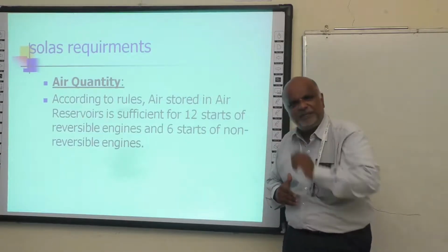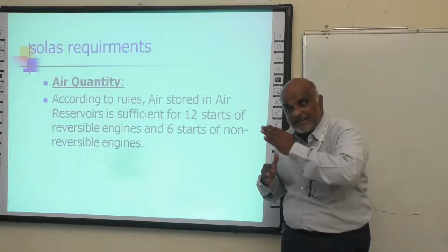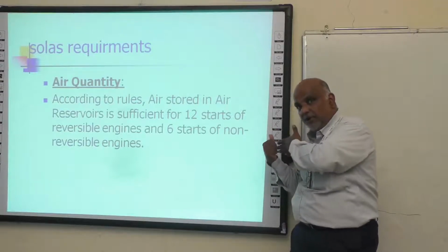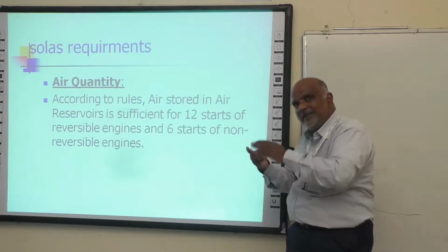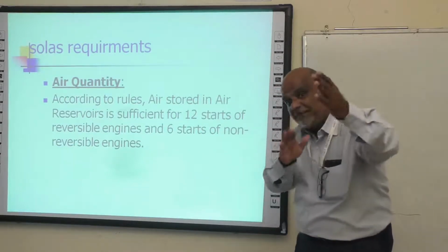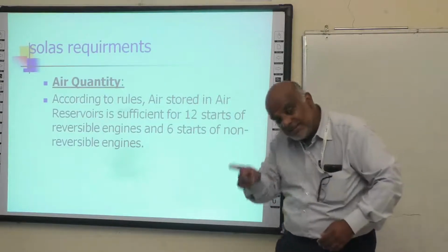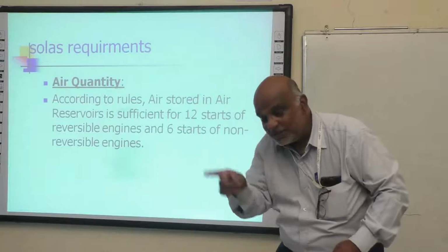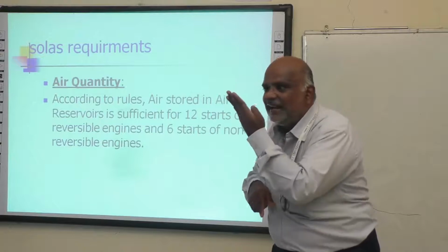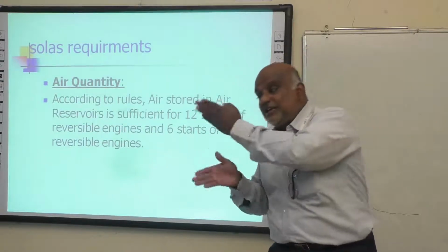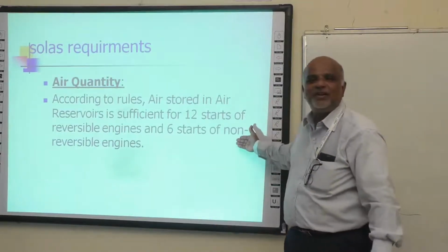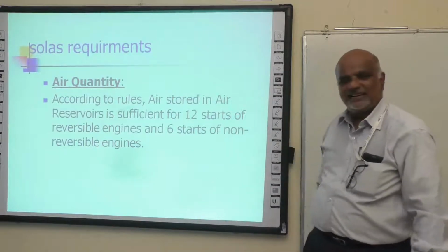By changing the direction of the pitch, you can run the engine in the head direction, that is, taking the water from the forward and pushing it behind. Also, you can run the engine in the astern direction. It can move by taking the water from the astern and pushing it forward. The engine is running in the same direction only. The propeller is rotating in the same direction, whereas each blade has changed its angle. That is all. Now, I have given a very good example for a non-reversible engine and a reversible engine.